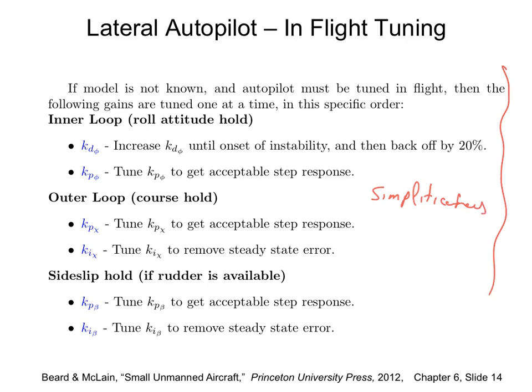So here the next step is to tune them, because we have made simplifications. All these 6 gains that you will need are computed from the previous slide, but you might need tuning when you put them into your actual simulator. The actual simulator is your 12 state S function that you already have.